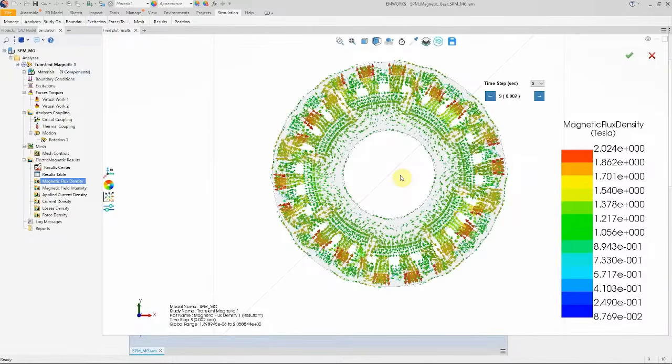And the shape of magnet itself, with creating curved edges or offset in the magnets, we can reduce the torque ripple. And again, pole pair combination will affect the torque ripple. In the same gear ratio, different pole pair combinations will increase or reduce the torque ripple.